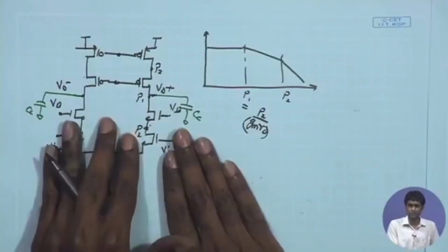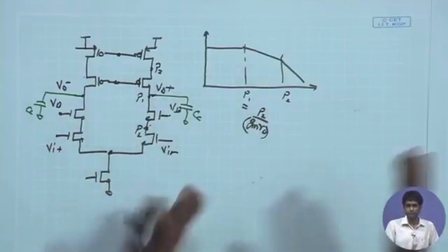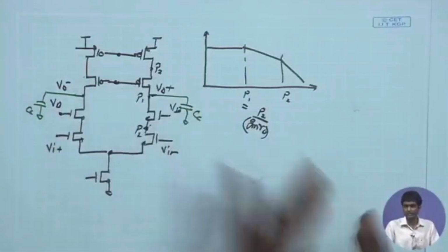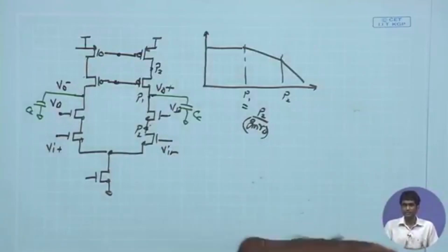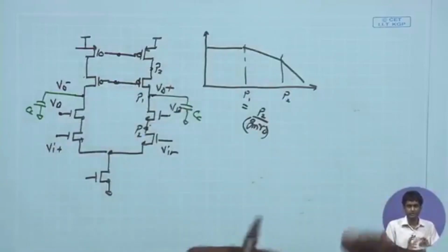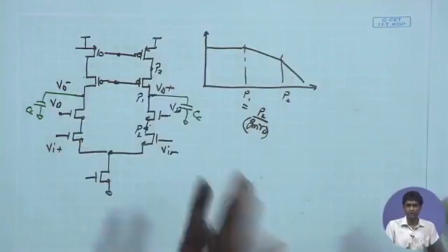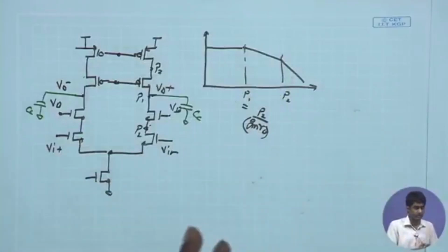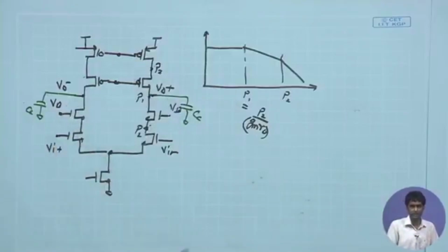This cascode amplifier has the property of self-compensation. You don't need to worry about the insertion of Miller capacitance, which leads to other complications. We have discussed other complications related to the arising of a zero, and then we need to figure out techniques to cancel out those zeros by inserting buffers or by inserting the nulling resistor, which again has to be controlled. So it leads to a lot of complications definitely, but here we see that it is able to self compensate and mitigate the instability issue.